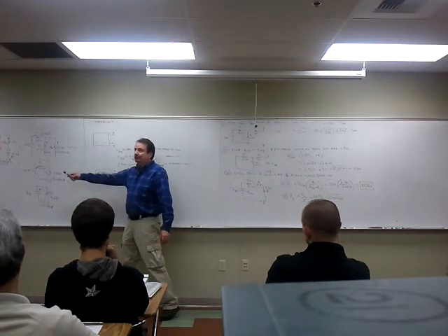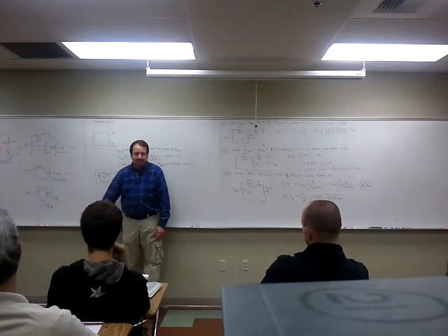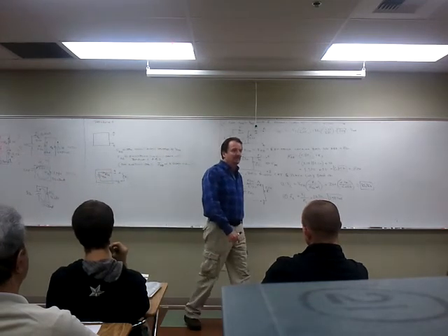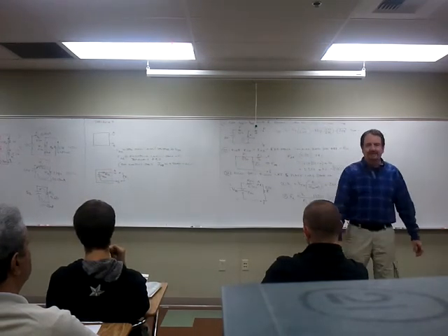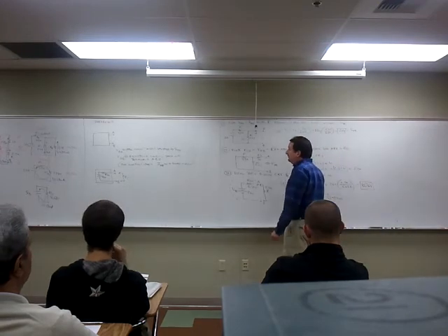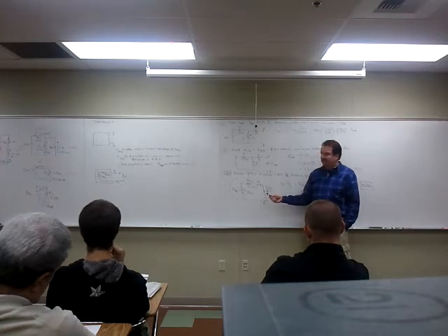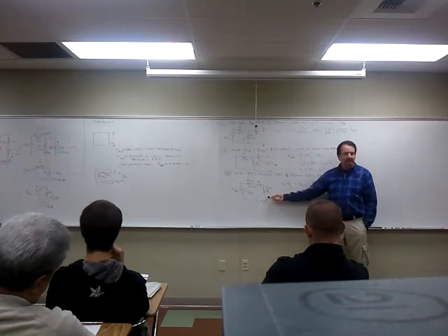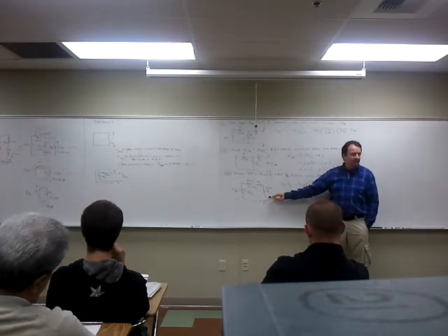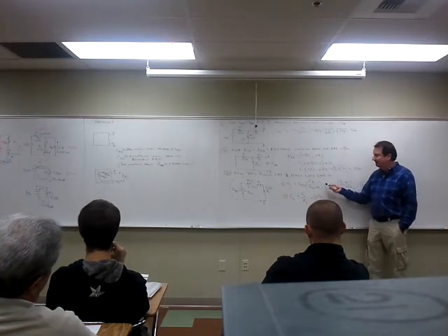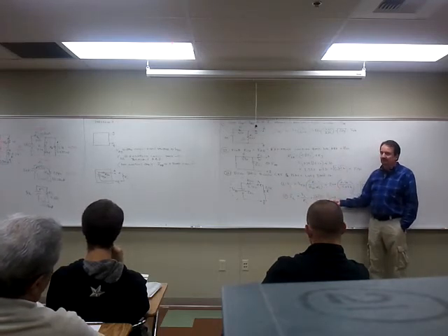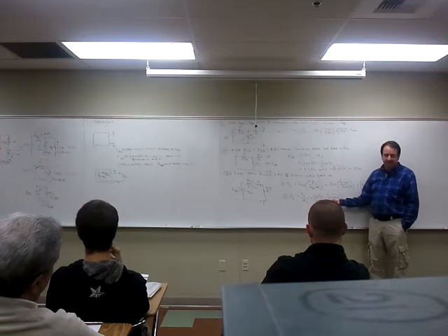And what if it was 30 steps to get to that? Well, 100 times 30, you're up at 3,000 steps to do that. But alternatively, what if I found the Thevenin equivalent? Then I put in a different load resistor 100 times here. How many steps do I have to do to compute it? Only 2. Isn't that better than 30?